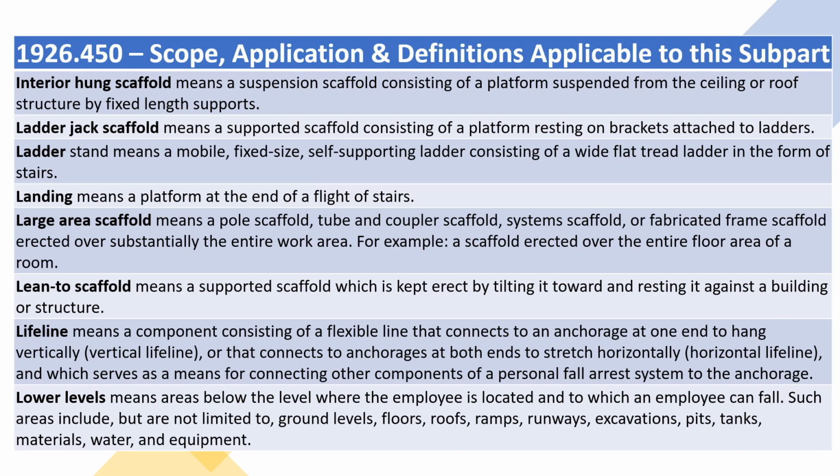Ladder stand means a mobile, fixed-size, self-supporting ladder consisting of a wide flat tread ladder in the form of stairs. Landing means a platform at the end of a flight of stairs. Large area scaffold means a pole scaffold, tube and coupler scaffold, systems scaffold, or fabricated frame scaffold erected over substantially the entire work area. For example, a scaffold erected over the entire floor area of a room.